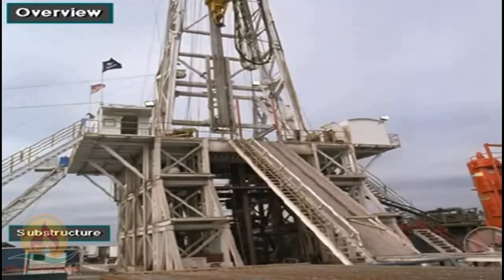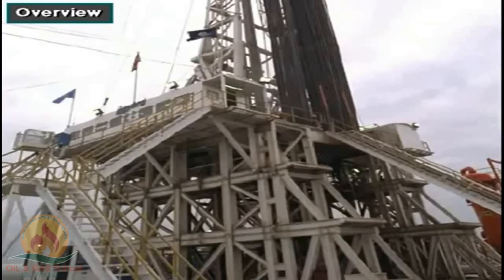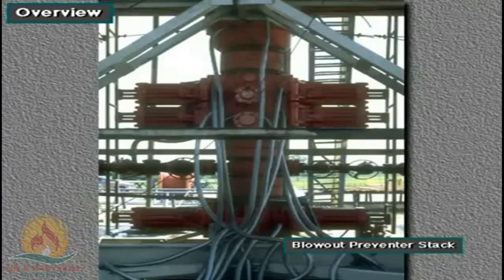The substructure is a rugged set of beams. It supports the mast or derrick and the heavy hoisting and rotating equipment. It also supports the drilling tubulars on the rig floor. It must be high enough to accommodate the blowout preventer stack underneath the rig floor.